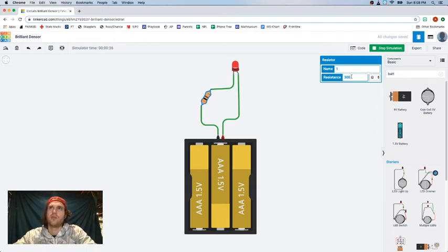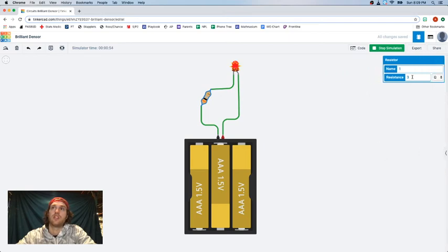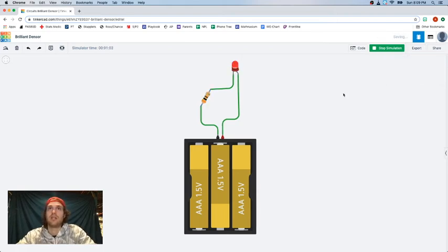I'm not sure if this is one of them, but I think if I change this to a 30 ohm resistor, it says, hey, look, you are currently operating at 63 milliamps on your LED, and that's too high. If I change it to 3, it shows the LED breaking. If you were to just hook up the battery pack straight up to the LED, it would be bad.